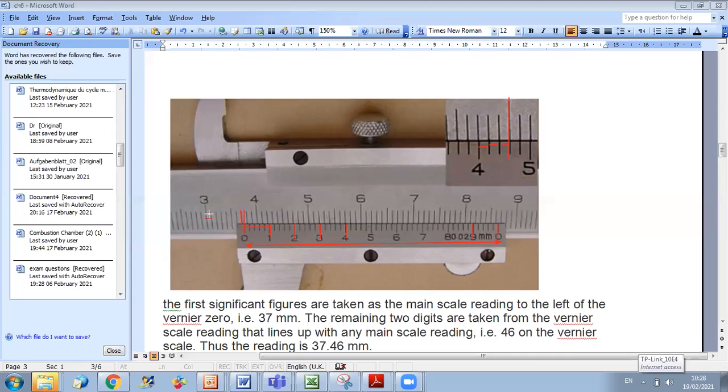That means you are dividing 1 millimeter into 50 parts, so you are able to read up to 1 over 50 equals 0.02 millimeter. Okay, for example, if you have the perfect match at this level, what do you read? You read 0.02. If you have the perfect match here, 0.04, 0.06, 0.08, and 0.1, etc. Okay, here it's 0.12, 0.14, 0.16, 0.18, 0.20, etc. Okay? Okay, thank you.